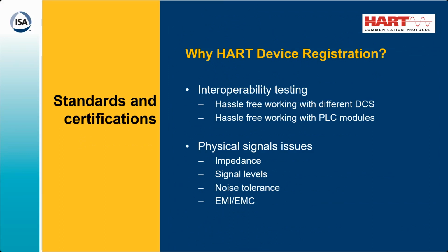Plus you also have the HART registration. All the devices which are connected are registered with the HART communication. Plus those devices are tested for impedance, signal levels, noise tolerances, EMI and EMC. So all these instruments which are connected in the plant have reliable HART communication with your plant network. So that's how the HART network has evolved in the last 30 years.